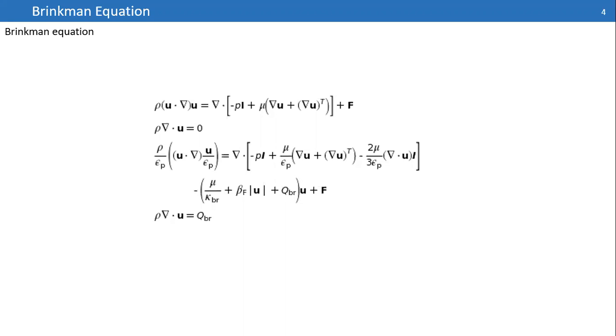Someone may ask me, okay, why are we not considering particles separately and then solving equations for each? The question is, you have a real bed, you load a lot of particles inside, and if you wanted to solve them individually, you should define a no-slip boundary condition on the surface of each of them, and it loads a lot of computational cost, and it's not easy to solve.